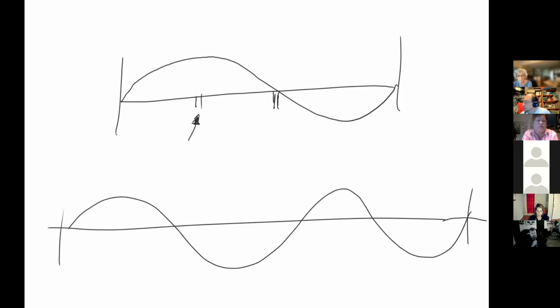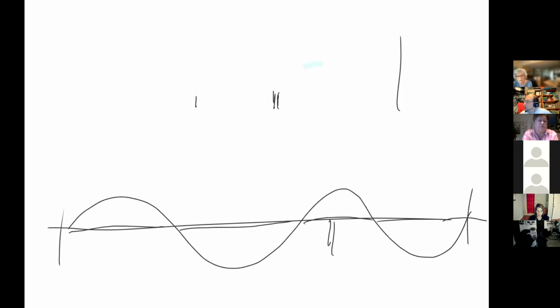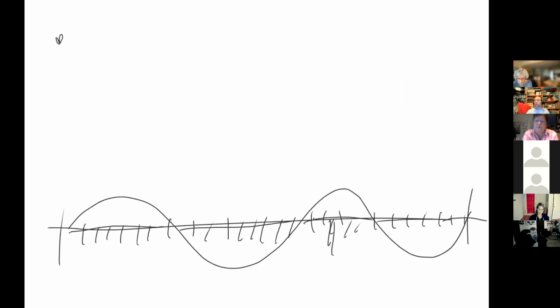What ends up happening is that, let's say you're feeding it right here, the different sections, if you go through modeling, will actually, like, the way you would figure out what an antenna pattern looks like is that you would just pick a random point in space and look at little pieces of current and see what kind of energy, electromagnetic fields they generate, and then add them all together.